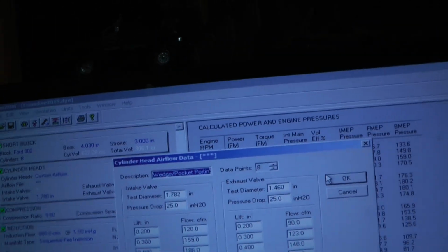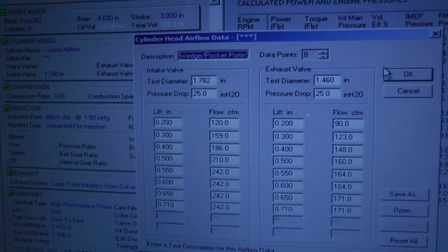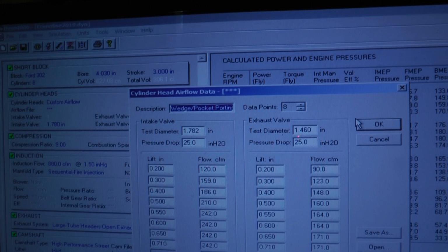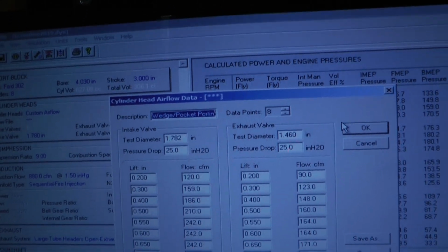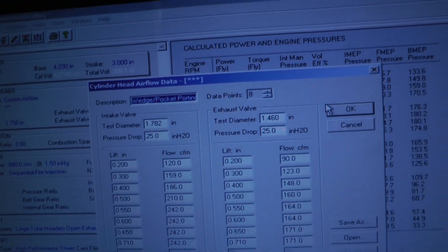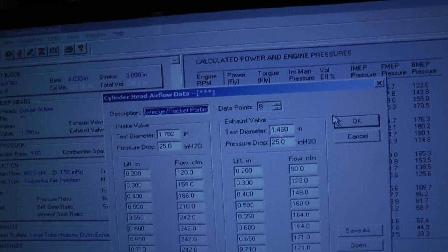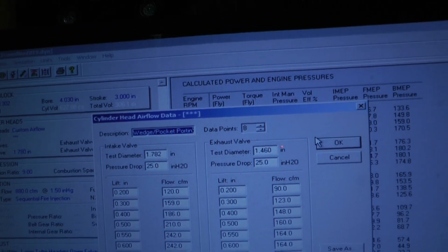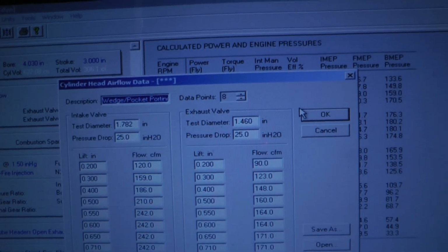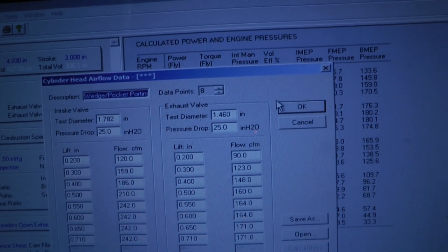So, this is a Truck 5.0, it's EFI. It uses the dual throttle body, the tall plenum. Those long runners are for low-end torque. I have a BBK, I'll show photos of that, a BBK dual 61 millimeter, so it's a lot of airflow. 122 millimeters is like an aftermarket throttle body for the last generation GT500. So I had to port match that throttle body. And then I opened up, and I'll show photos of opening up the dog legs.